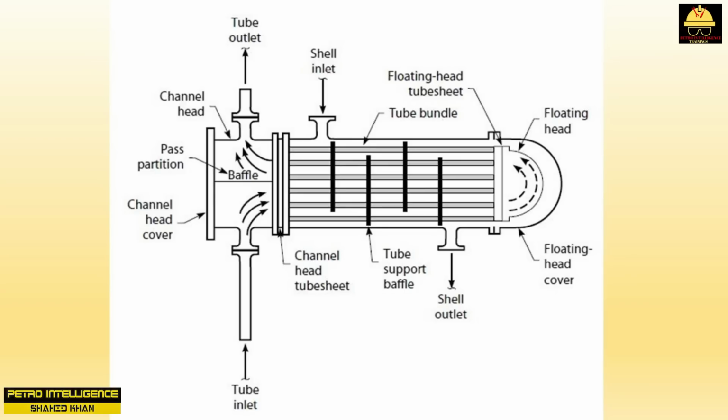The tube side flow enters the bottom of the channel head. This assumes the cold fluid to be on the tube side. The cold fluid may be on the shell side or the tube side of an exchanger. The convention is to put the cold fluid nozzle on the bottom of the exchanger. Sometimes this is necessary. Sometimes it does not matter, but it is still the convention.